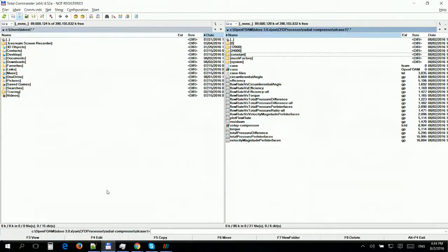You would need to import your new mesh to OpenFOAM. By the way, you asked about the format. The Fluent .msh format is the best. We have great experiences with it. You use a special utility, fluent3DMeshToFoam, and the file should be ASCII, not binary, and it usually works very well.